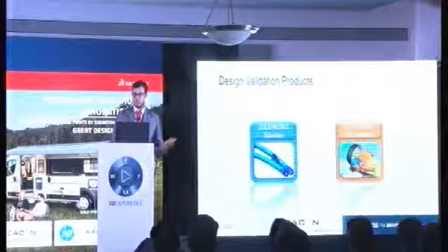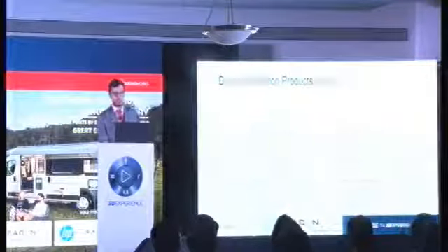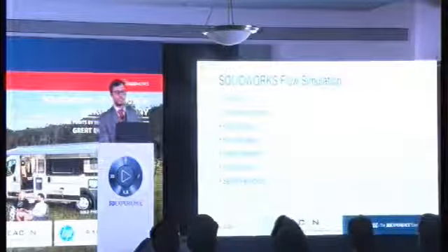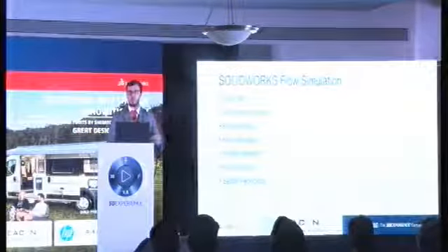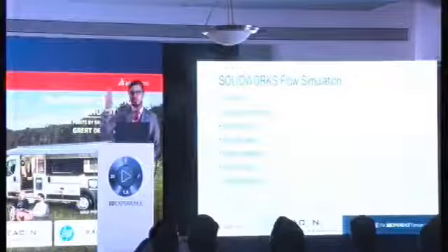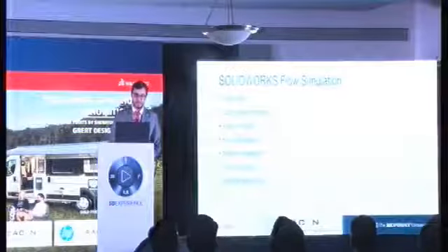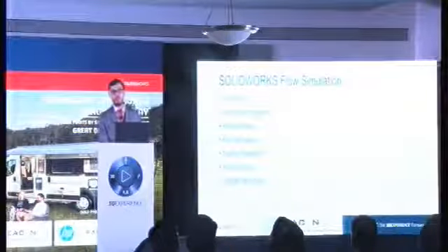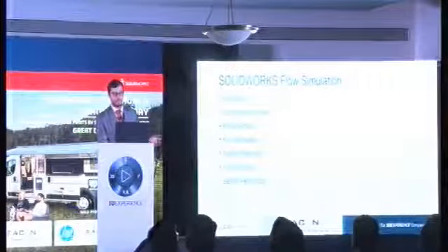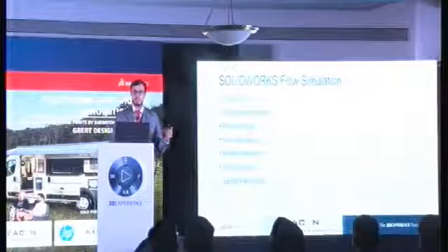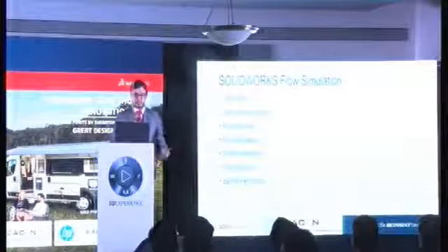Now let's move into the second part, that is SolidWorks Flow Simulation. SolidWorks Flow Simulation has a new color bar option where you can align your color bar vertically or horizontally. From the component explorer, you can directly define the material from the tables. We have the free surface tool, we'll see about it in the next slide.